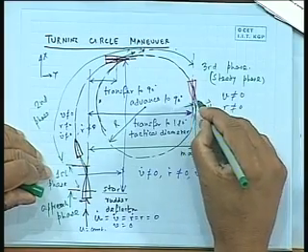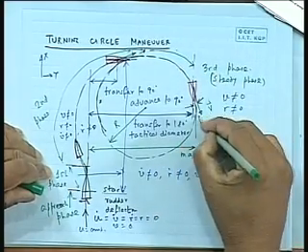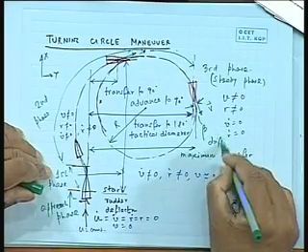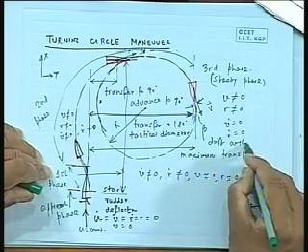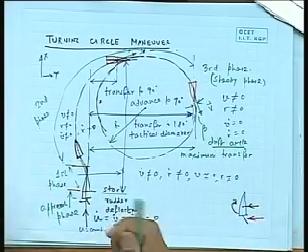So, there is a so called beta angle, that is this angle, there is drift angle. Speed vector is here, the heading is there. This is my drift angle, beta, the drift angle. Drift angle has to be non-zero for a turn. If it is not non-zero, it cannot turn. It is not like a car, it can turn. It has to turn like a plane or something like this. There has to be a heading angle.